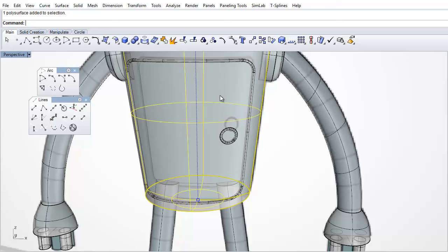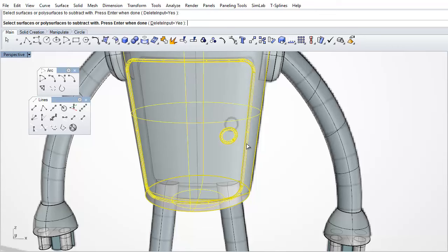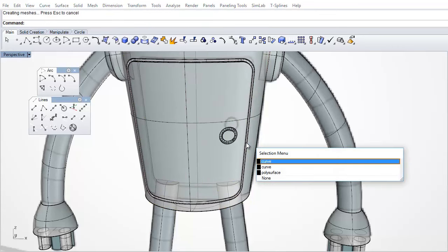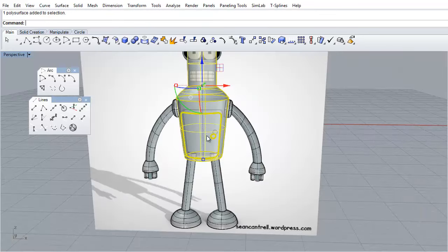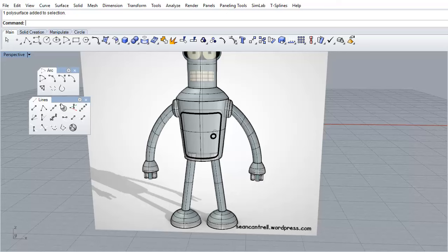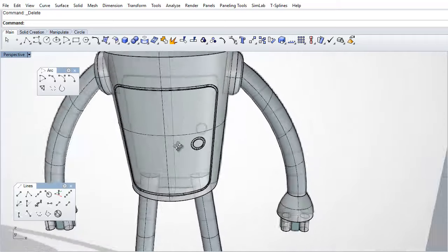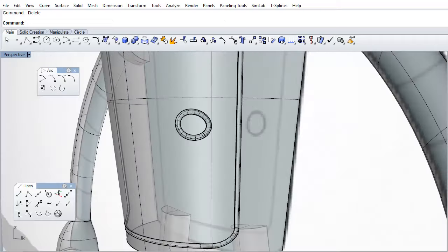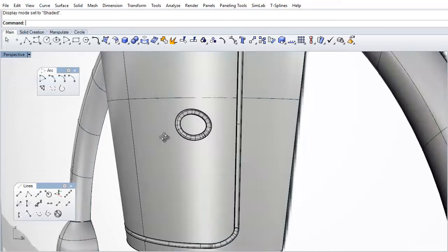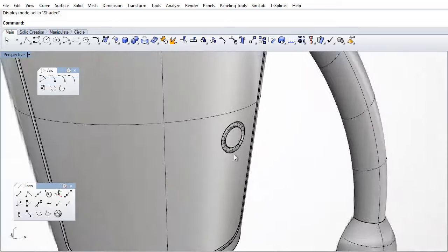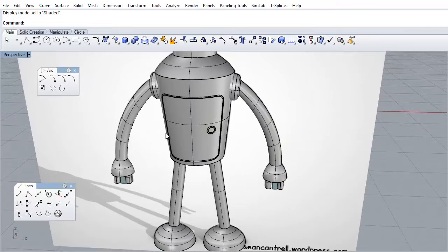So I'm going to take the model, I'm going to Boolean difference, BD, this piece of geometry and this piece of geometry. Alright. Let's move this out of the way, and then we're going to grab those bits and pieces and delete them. Alright, so what you have is sort of a curvature, a hollowing going into the body at the moment. Let's shade that up. You can see it's sort of cut out a groove, so it looks like there's a door handle in the front.